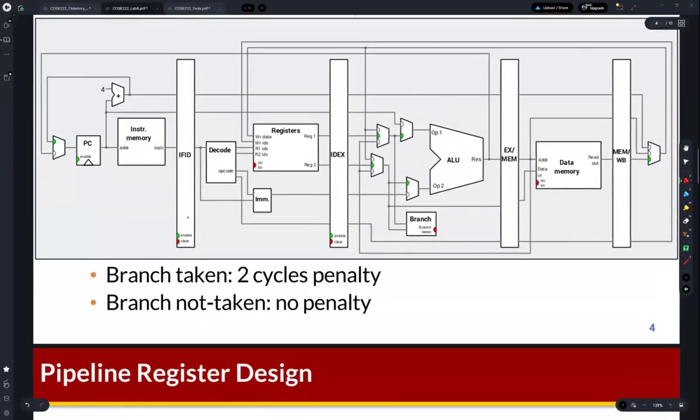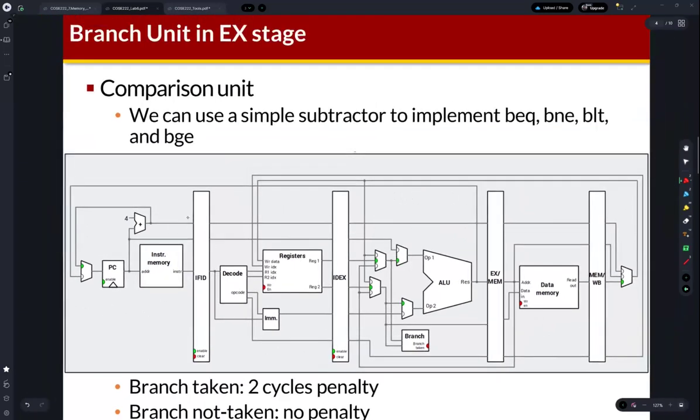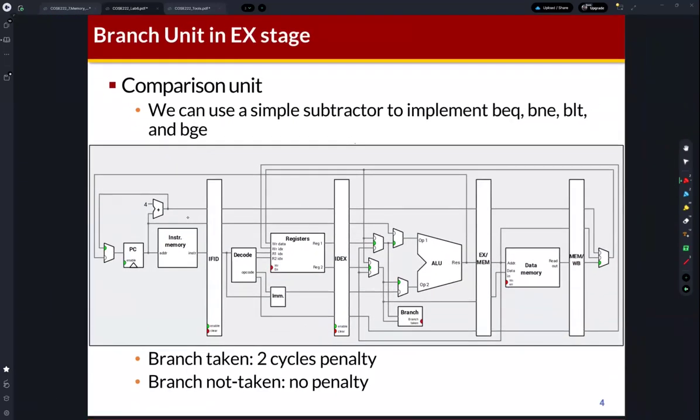And then, as I mentioned in the class, in the textbook, in order to reduce the control hazard, you can find the equality check logic just after the register file. But I mentioned that in order to implement this, we need to define more complex hazard detection, right?